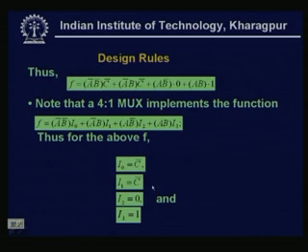So, already we have seen this is my function. If we want to realize it using a multiplexer, that is a 4 to 1 multiplexer implementation, because I have selected two control lines or select lines, and for 2 control lines there will be 4 primary inputs, they are C bar, 0, 1.